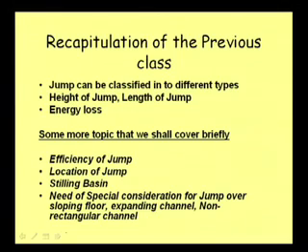Then we started a discussion about the energy loss, how the energy gradient line suddenly drops in the hydraulic jump portion. On the upstream of the hydraulic jump, if we neglect other losses, head loss is insignificant. At the downstream also, head loss is insignificant if friction loss and other things are negligible.